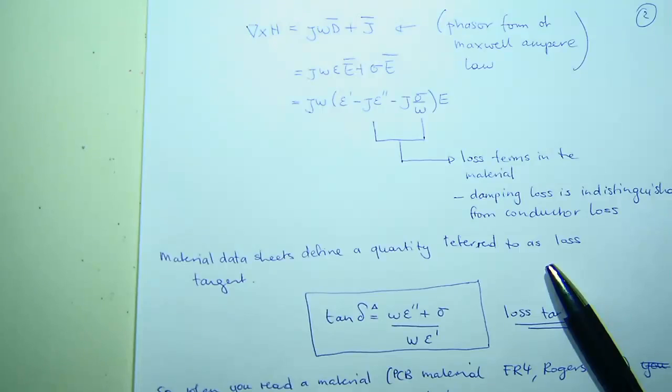But when you look at it, what usually they give you in the data sheets is the dielectric constant, which we'll find out why that's relevant, including working out what an impedance is or how to make matched impedance lines on that PCB. But they also tell you what the loss tangent is.